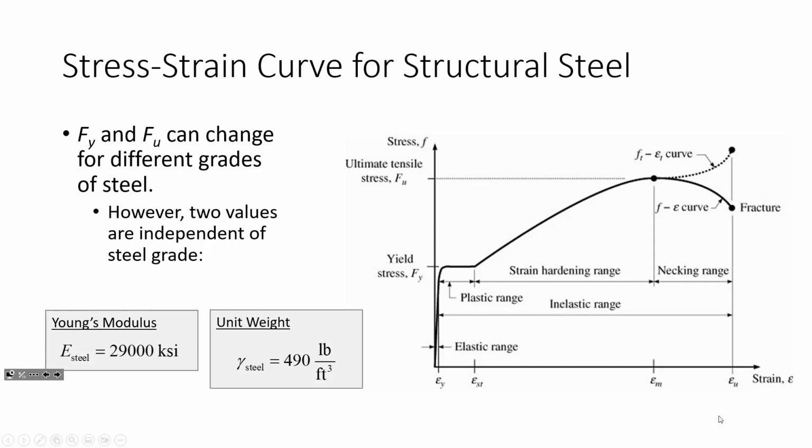It's called the elastic perfectly plastic region, where as we've loaded it, those molecular bonds start to fail, and the element starts to freely deform under a constant load. But as the element is deforming under that constant load, those molecular structures are realigning, and once we hit a certain point, the element can start accepting load again. And so that's what we call the strain hardening range.